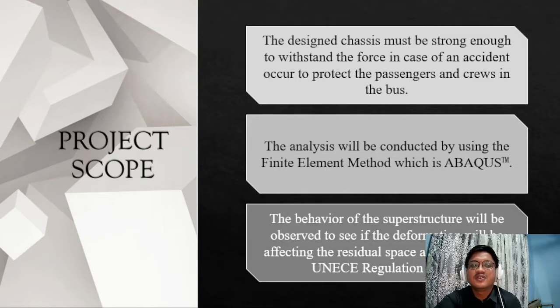The analysis will be conducted using the finite element method, with the Abaqus software. The superstructure chassis were designed with various configurations in Abaqus. The behavior of the superstructure will be observed to see if the deformation affects the residual space, according to the UN ECE Regulation number 66.